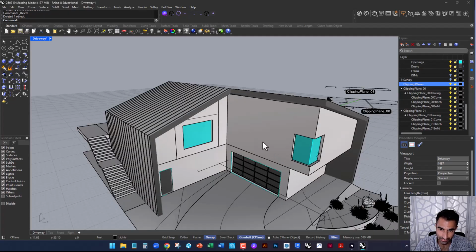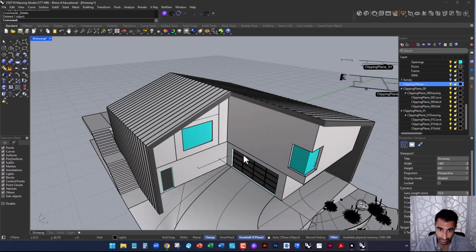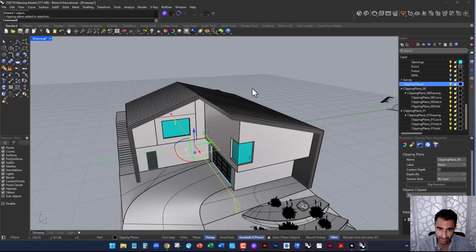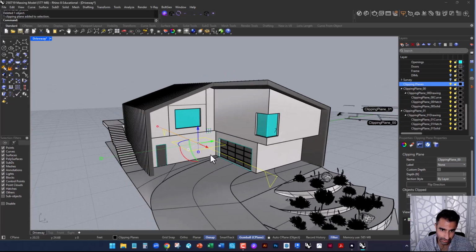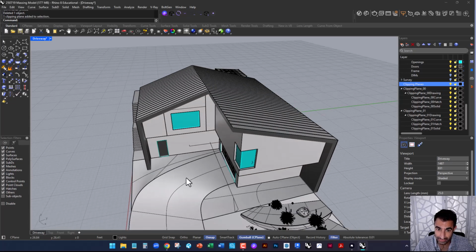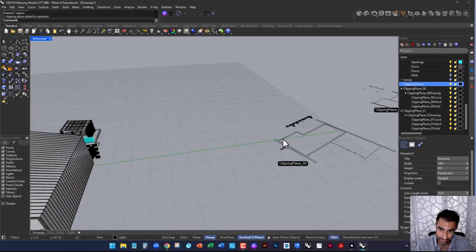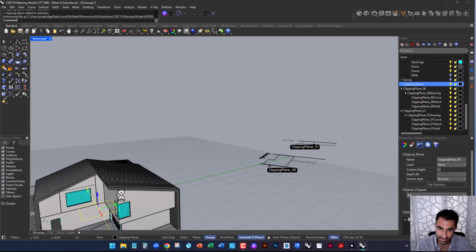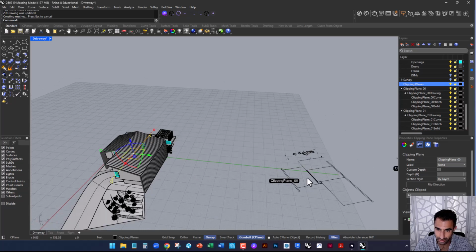So I'm going to go over a workflow where I take drawings from Rhino. This is a model that we're currently working on. We have a clipping plane. In most floor plans, we're taking a cut at 4 feet above the finished floor level. So I can create a clipping plane at 4 feet. I can do that for either plan or section. And Rhino 8 has what are called clipping drawings. As I create my clipping plane, I can actually update this and watch the clipping drawing update.